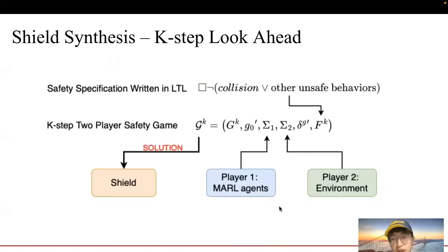Now we talk about how to synthesize the shards. We propose a method called k-step look-ahead shard. First, we write the safety specification in linear temporal logic. Basically, it's always no collision or other unsafe behavior. And we leverage domain-specific knowledge to get the abstraction of the agents and the environment and construct a two-player safety game. To win this game, at each time step, the state should satisfy the LTL safety specification, and we construct the shard by solving this game.